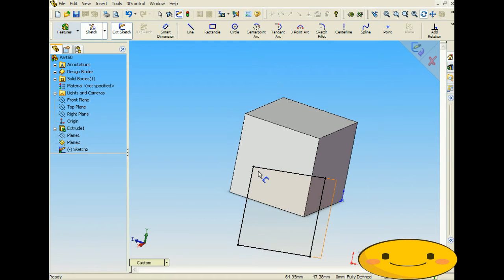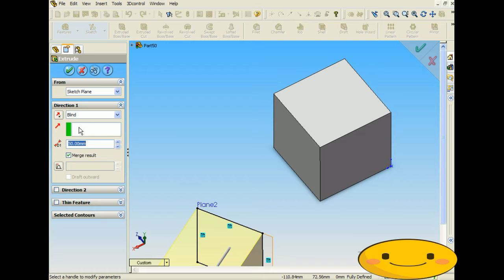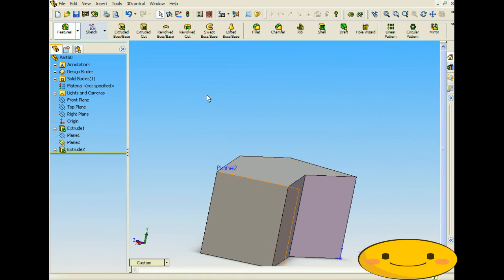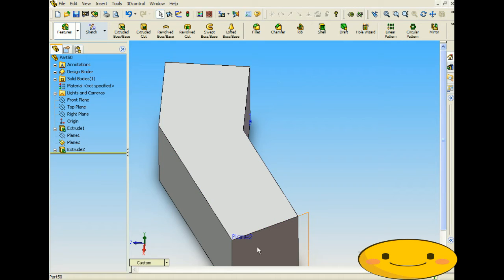And now, let's say that we wanted to extrude this. This is going to extrude directly onto those two points, like onto these lines. So when we go to extrude it, it's precisely in the right orientation, the right direction and everything. So it works out very nicely when you convert entities. So let's click Feature, click Extrude, and let's flip it around just so it goes through. Click OK. And you can see that as we extracted those points out of the sketch, it came out perfectly from our extrude. It went perfectly into our original solid that we came out with.